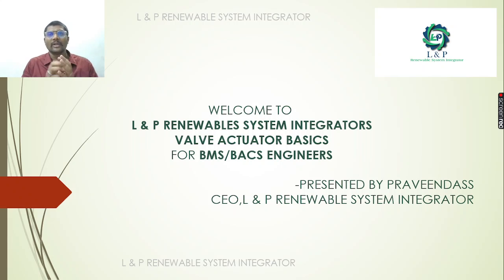For the operation of a valve, manually we were opening valves. If it is a big valve or a small valve, it is easy to open it manually. But when it comes to a plant like a chiller water plant or heating, ventilation and air conditioning plants, the chilled water valves might be located at remote locations, so it will be difficult for some person to go and open them manually. In such places, we use valve actuators.